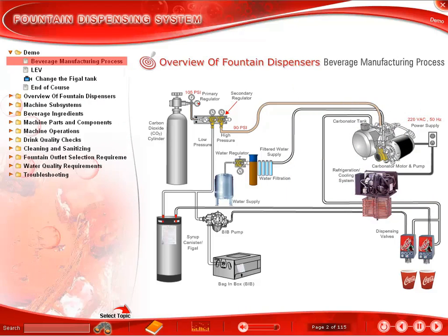Water makes up over 80% of the beverage, so both the quality and quantity of water is important. The typical post-mix dispenser requires water volume of 100 gallons per hour to meet typical operating demands and maximize the efficiency of the dispenser. 40 to 75 psi of water pressure. A water source line at least ½ inch in diameter with a separate shutoff for the carbonator.